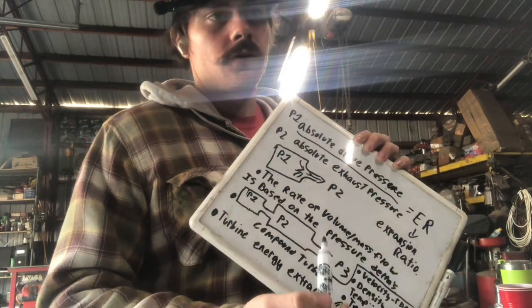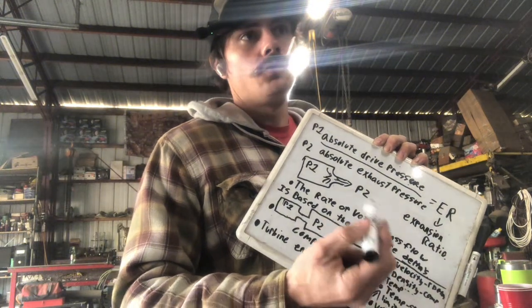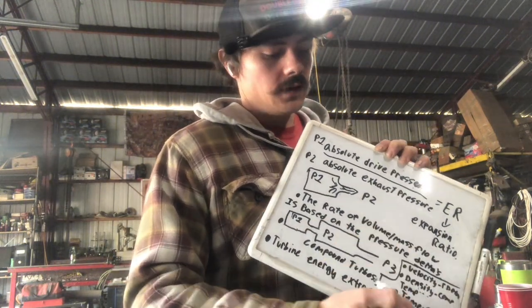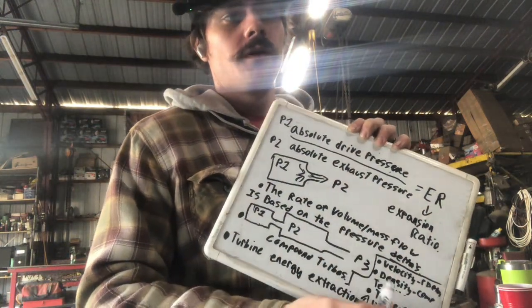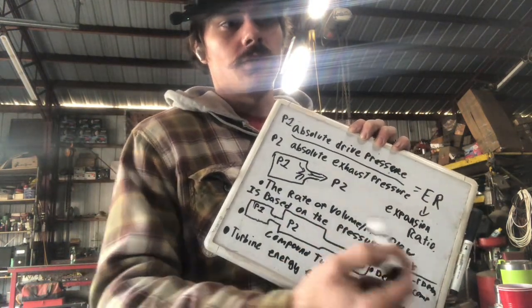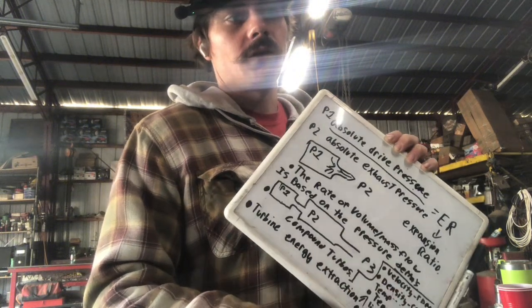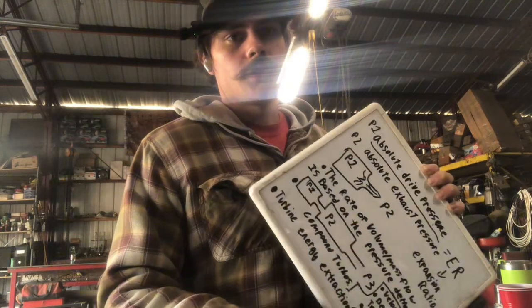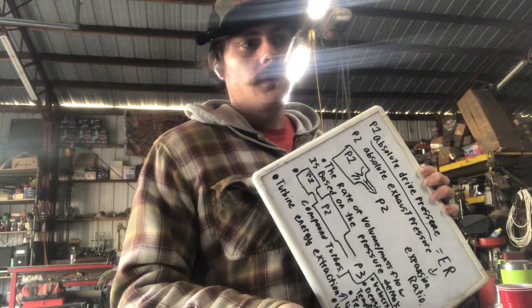And that's because the compressor size is allowing the turbine to get up to a turbine speed that makes the angle of attack very poor. So the ability to actually move the gas into the turbine wheel volute has become inefficient, instead of the velocity of the gas being inefficient. So there are two examples of where the turbine is having a problem, because the compressor can't hold on to it.